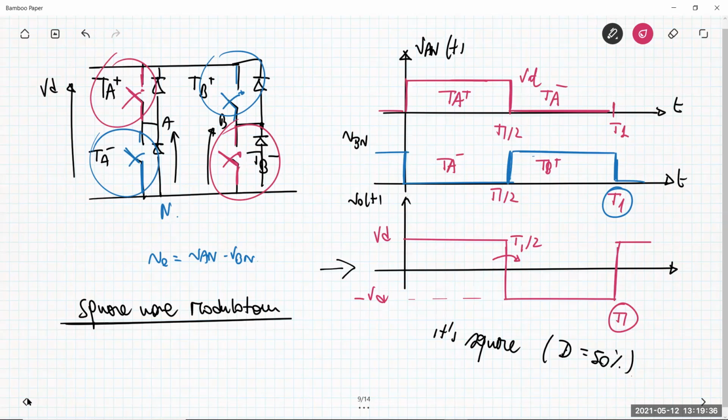Compare this situation in a period T1 with what you have, for example, for a linear pulse width modulator. There you have switching activity at the switching frequency, Fs, which is much higher than the frequency 1/T1. So in terms of dynamic power, the pulse width modulator dissipates large power with respect to this one.